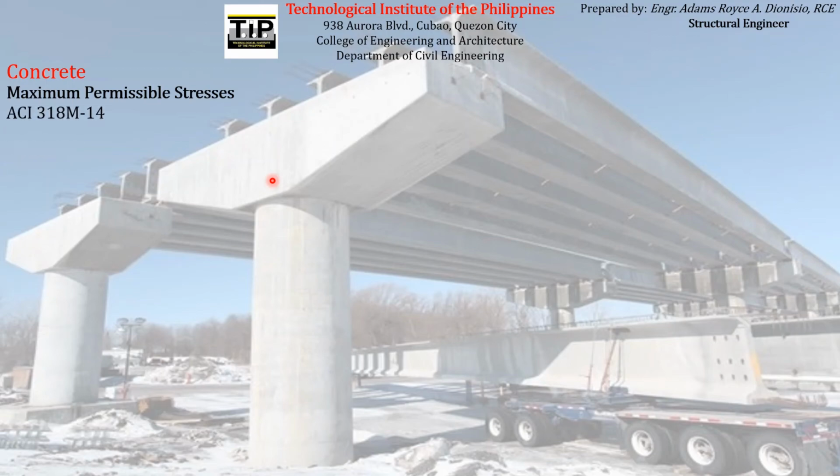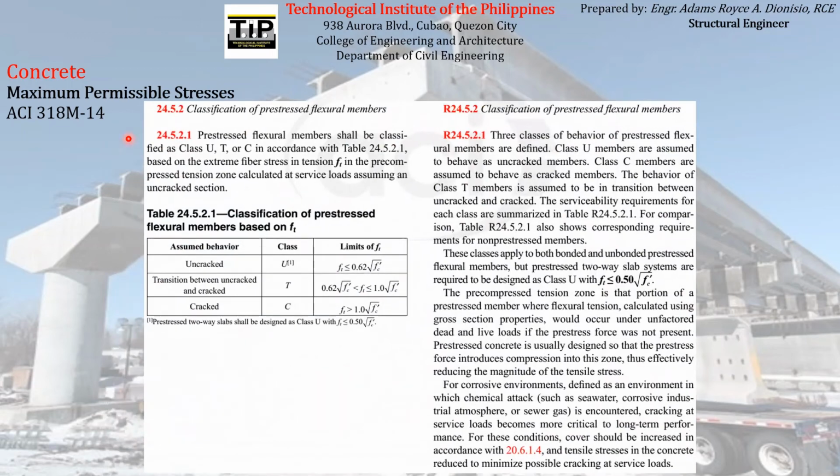If you refer to the ACI code 318M-14, section 24.5.2, the code specifies certain limitations in terms of stress that can be experienced by the concrete at certain stages of pre-stressing, because just like I've said before, we don't want to overstress concrete as we conduct pre-stressing activities. So the code specifies the maximum permissible stresses at each stage of pre-stressing.